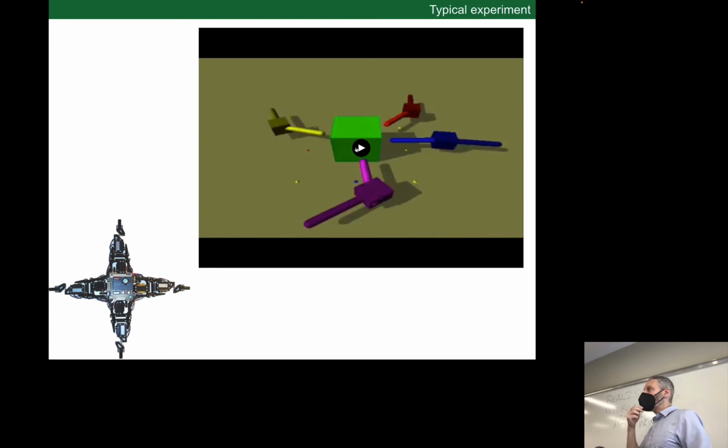We're going to now start up the estimation algorithm again, and it's going to try and evolve simulators, and it's going to evaluate each simulator twice. In the first evaluation, it's going to rotate motors 1 and 6 down. Then it's going to play back that body plan or that simulation again, but rotate motors 3 and 6 down. And it's going to get back two pieces of virtual vestibular data. It already has 2 pieces of physical vestibular data, and it's going to take the difference between both. And a good simulator should be able to reproduce the vestibular sensation in both cases.